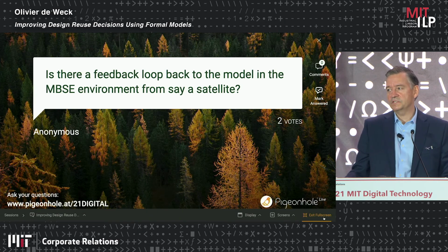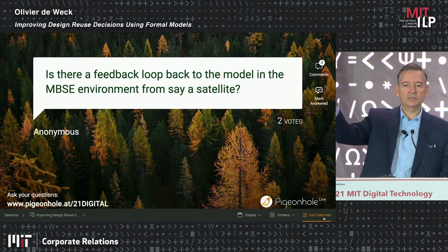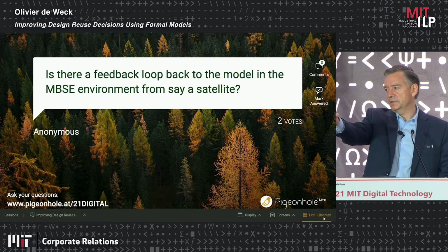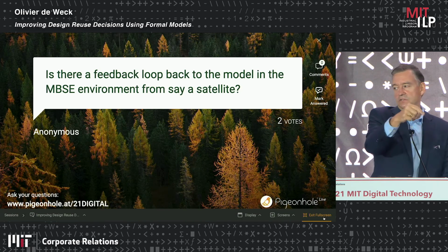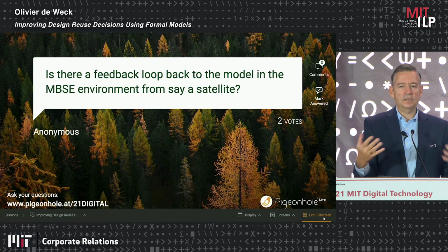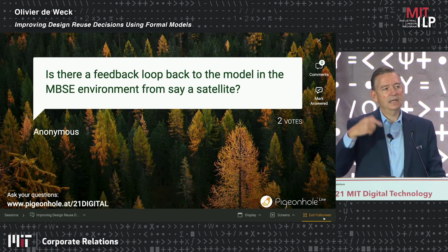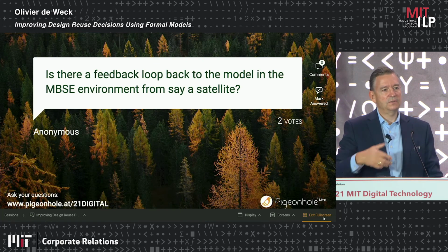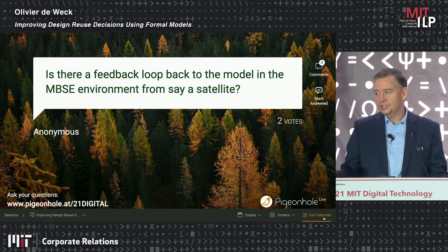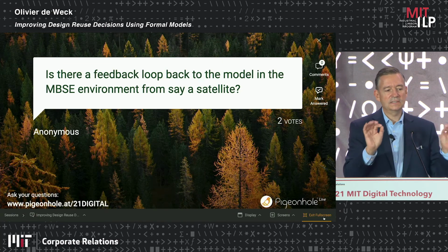Every one of their rovers exists as a virtual version, and before a command is sent to the actual rover, move over to that rock and drill a hole into it, you do that on the digital twin of the rover to make sure that the commands you're about to send are not going to cause some failure or some unexpected behavior. And as you do that, you improve the model, you improve its fidelity, you update parameters. Systems age and fail as well. You update that in the digital twin. So I think digital twin is the connection here.